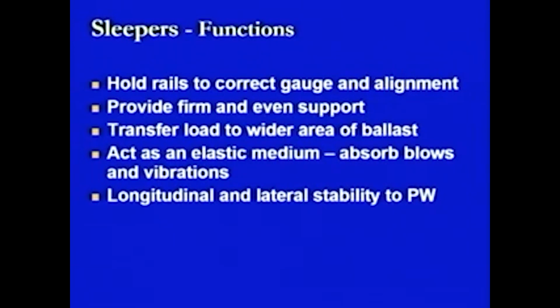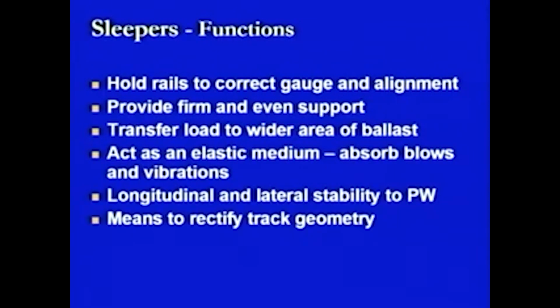If these forces are quite large, then the sleepers will come out of their position and will either move along with the rail section, or they will just lose the strength which they impart to the overall track structure. So, this is another aspect of stability. Both directional stability should be maintained.